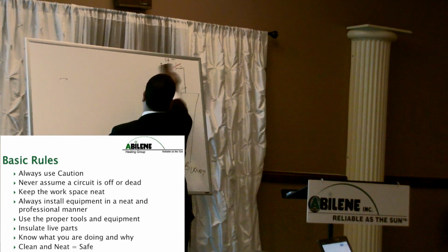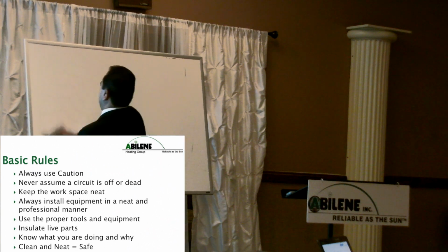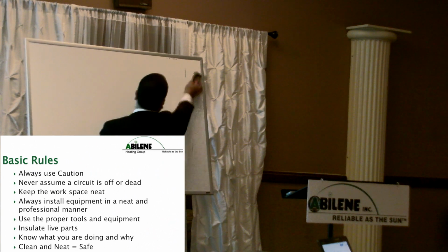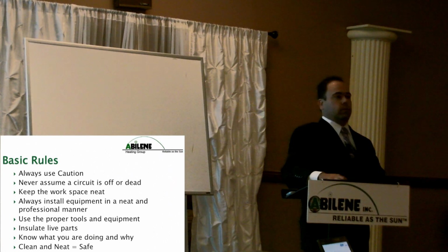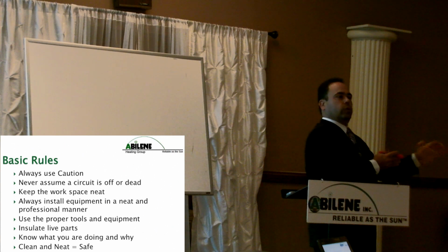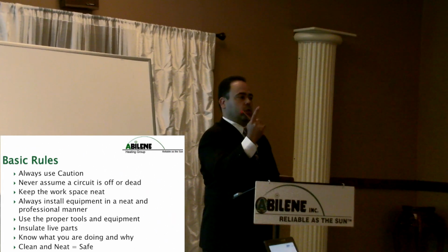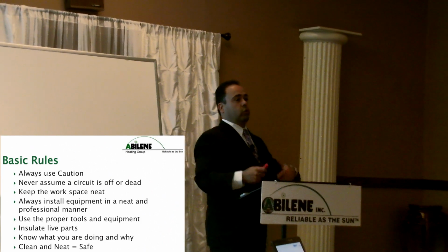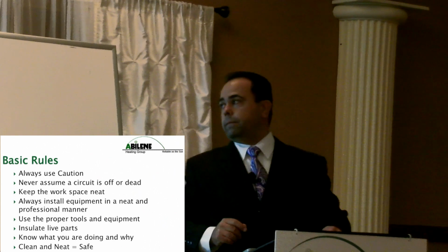Everyone see that and understand it? Everyone understand the difference between a series circuit and a parallel circuit? Real simple. In series, everything has to be closed in order for it to get to the end. In a parallel circuit, you only need one to close. So all of our limits, or our high limits, are always wired in series.